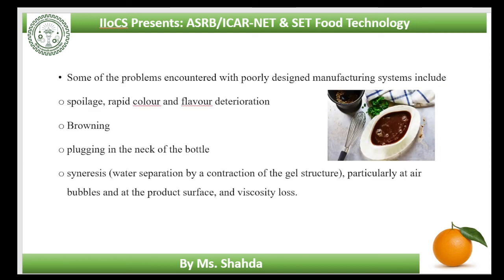Some of the problems encountered with poorly designed manufacturing systems include spoilage, rapid color and flavor deterioration, browning, plugging in the neck of the bottle, syneresis, that's water separation by a contraction of the gel structure, particularly at air bubbles and at the product surface, and viscosity loss.